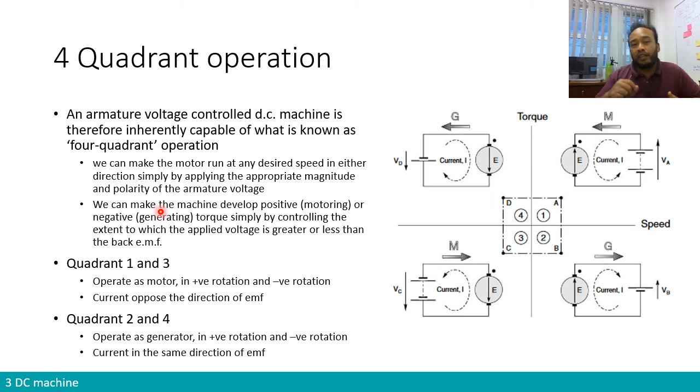So instead of having the torque to accelerate the machine, it is having a torque to decelerate the machine, to reduce the acceleration of the machine. Okay, so for example, if we are in this quadrant where we have positive speed and positive torque, it is basically the normal operating quadrant of a motor. So you are rotating the motor in clockwise direction and it is producing torque basically to accelerate the machine.